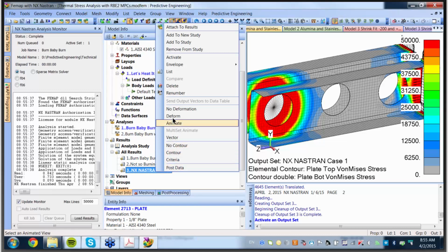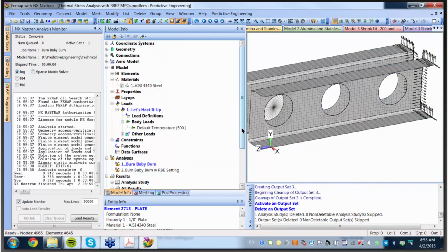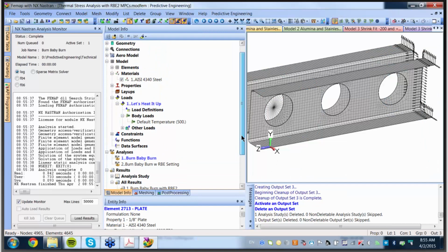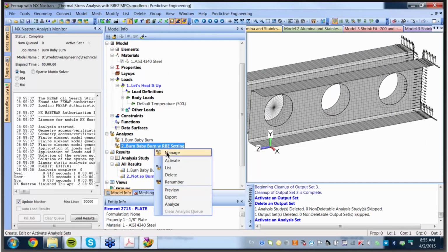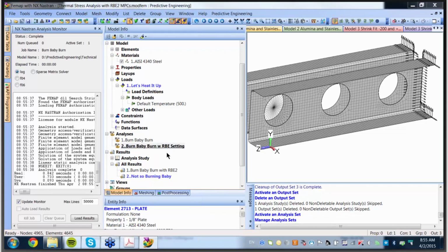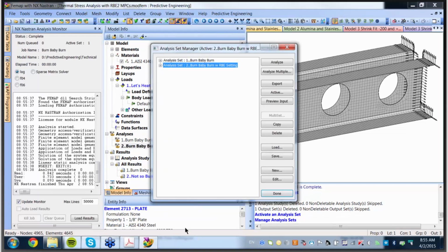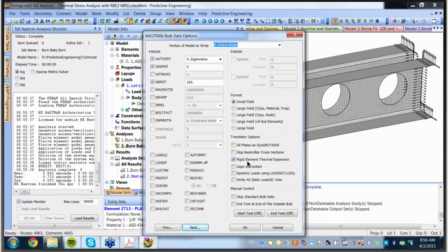Well, the reason it's still there, and the reason why it's a little sneakier than you would think, is that you actually switched the formulation of the RBE. The reason why you have to click there is because you're actually changing the element. It's no longer a multi-point constraint. Behind the scenes, it's a bunch of beams. They call it a Lagrange formulation. You agree with the theory, but so they swap out multipoint. They change it to beams, and then of course with the beams all set,